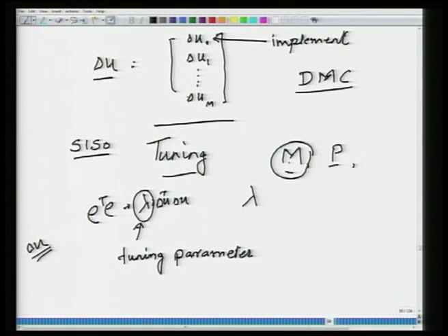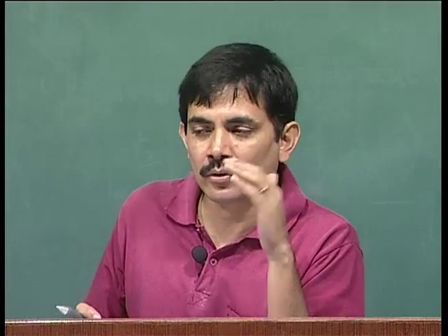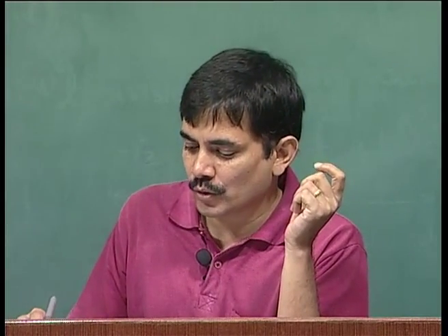If you choose too small a value for the control horizon, then the controller can only make so many control moves to ensure set point tracking or close reference trajectory tracking. That being the case, if this is small, your controller becomes aggressive. It will try and make all the moves that are necessary, so that in the future the error in the predicted output is as small as possible. So, small M's will lead to an aggressive controller, large M's would lead to a sluggish controller.